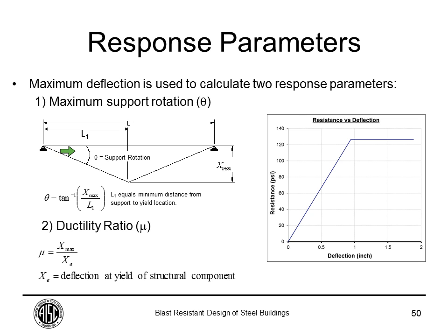That's one parameter. The second parameter is the ductility ratio, which is the ratio of the maximum deflection divided by the deflection at yield. Again, this is a measure of the level of plasticity. The reason that you use the 2 is just to control different combinations that you could find in a building.